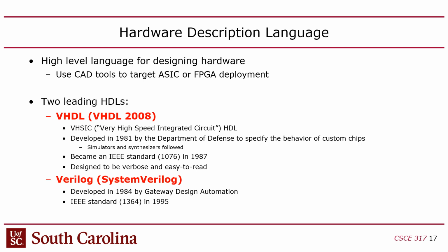Now, the downside of that is that in order to test your designs, you're going to have to synthesize them onto the FPGA and then put probes on the FPGA to watch what the signals are doing, right? The problem with that is that it increases the iteration time.